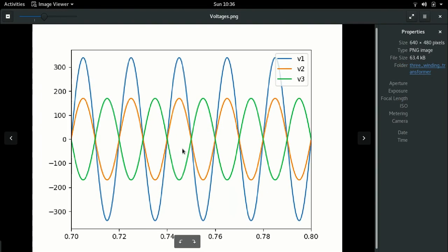So since we have a step down transformer with a 2:1 ratio for both the secondary, or rather you can say winding 2 and winding 3, we do see that the voltage in the primary is double the voltage in the 2 secondaries, right, or the secondary and the tertiary. And moreover, we saw that because of the dot polarity of the tertiary winding, the voltage at the tertiary winding is 180° out of phase with respect to the primary and winding 2.